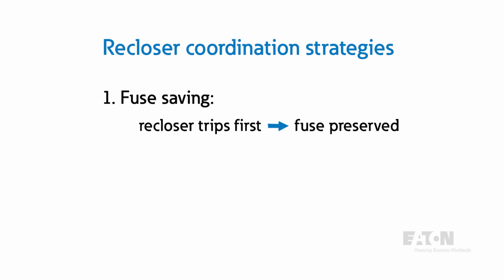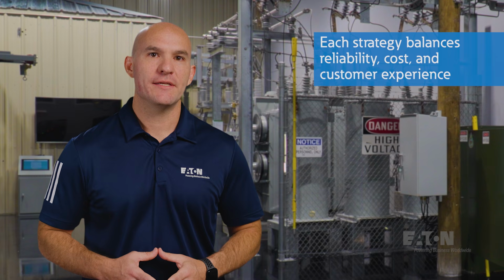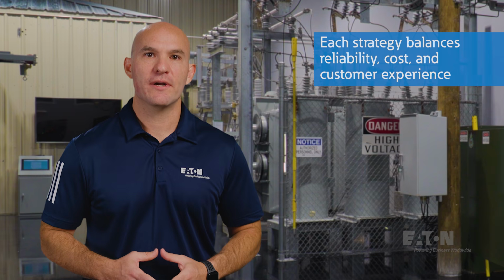The first is fuse saving, where the recloser clears the fault before the fuse operates. This approach preserves the fuse and avoids a service call. The second is fuse sacrificing, where the fuse is allowed to operate first. This helps prevent blinking the entire circuit, keeping service more stable for unaffected customers. Each strategy has trade-offs in reliability, cost, and customer experience.